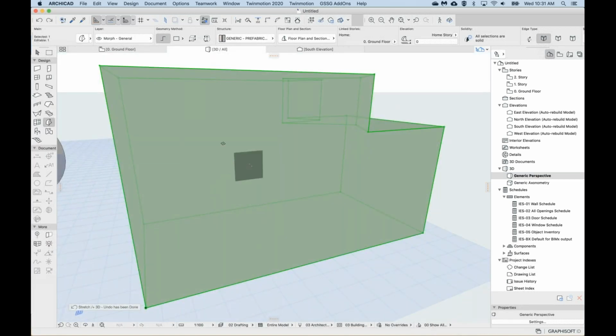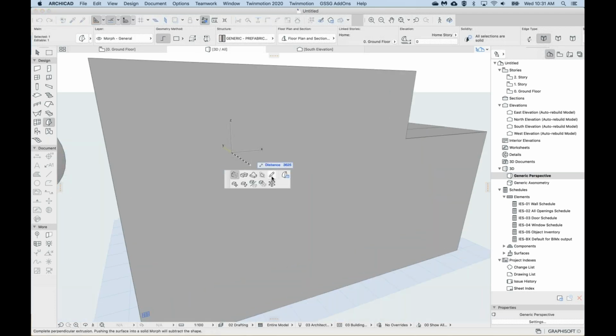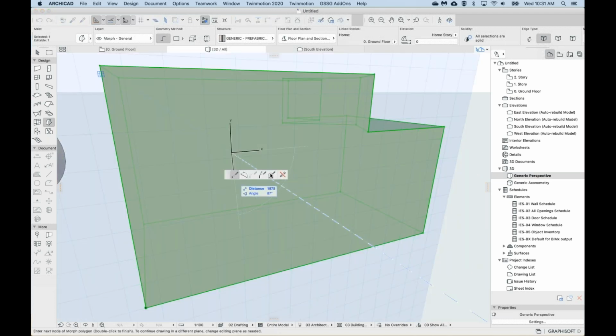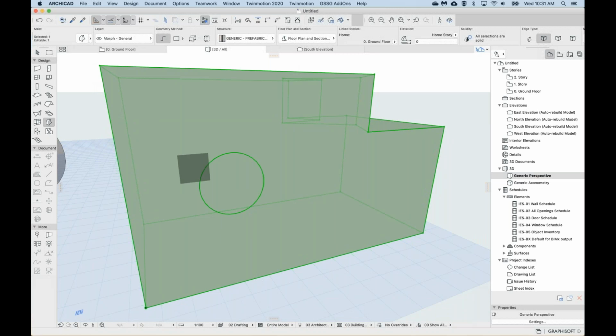Done. Wow, well done. So instead of using box, because this will just make a rectangle, I will draw using the polyline tool, clicking on the surface, using the pencil. From the pencil, I need to choose the last option, so I'm going to draw a circle with the last option. The first click is one of the points on the side, and then we choose the center point. Then I need to say go around 360. So basically I'm just drawing a 2D circle.